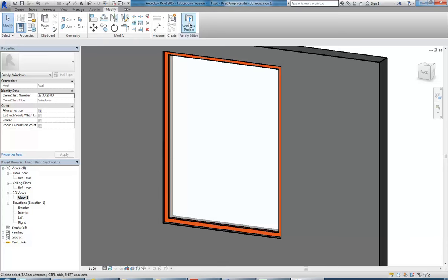But then, if you do want to have the option of turning them off, anything in Revit, you can select it and then go to here, you've got this visible option. So you can add that as a parameter. You can add there, add parameter, transom, which one did I select? Transom 2, I think it was.